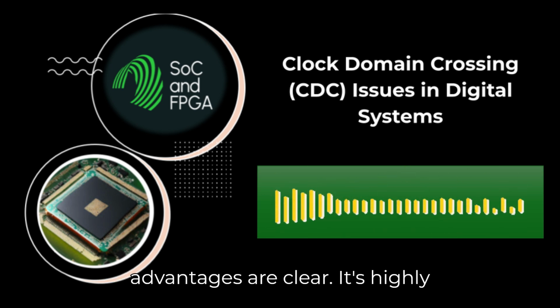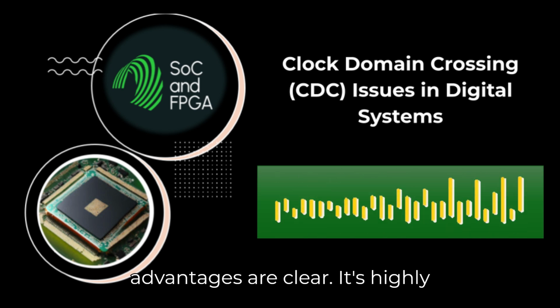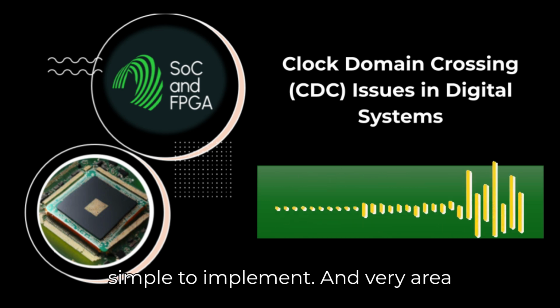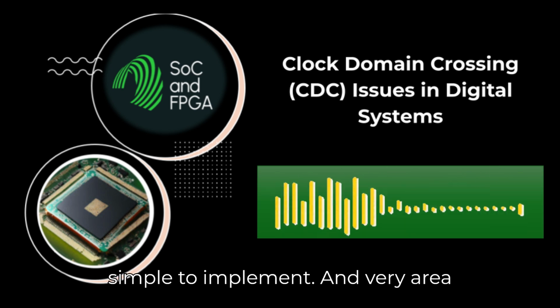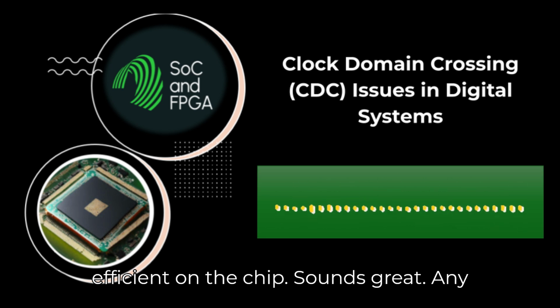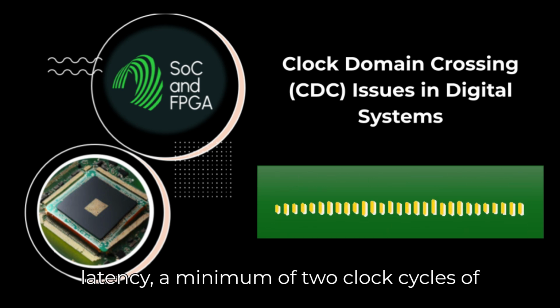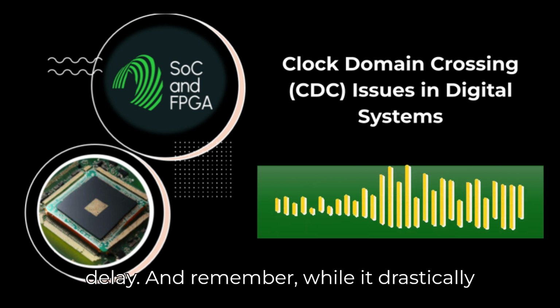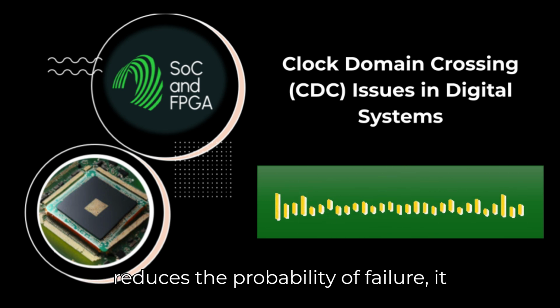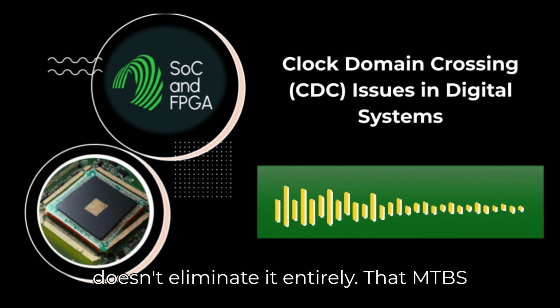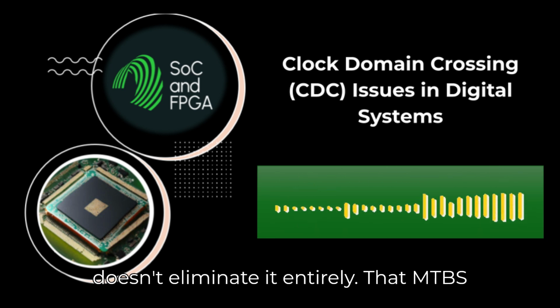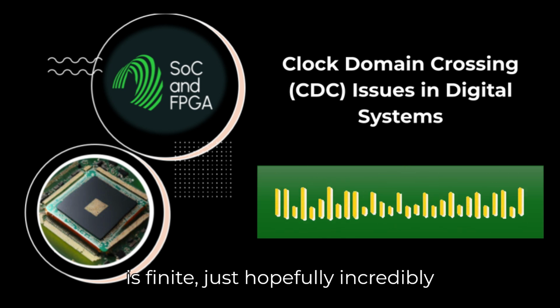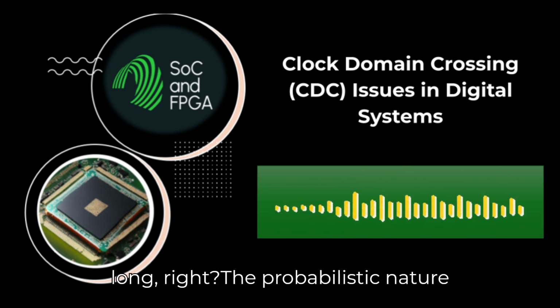Hopefully, yes. The advantages are clear. It's highly effective for these single bits. It's simple to implement and very area efficient on the chip. Sounds great. Any downsides? Well, it does introduce latency, a minimum of 2 clock cycles of the destination clock. Okay, a slight delay. And remember, while it drastically reduces the probability of failure, it doesn't eliminate it entirely. That MTBF is finite, just hopefully incredibly long. Right, the probabilistic nature again.